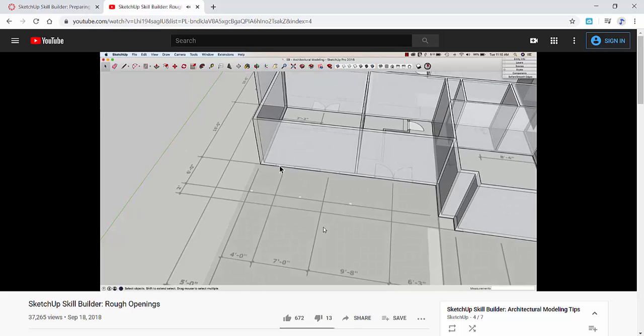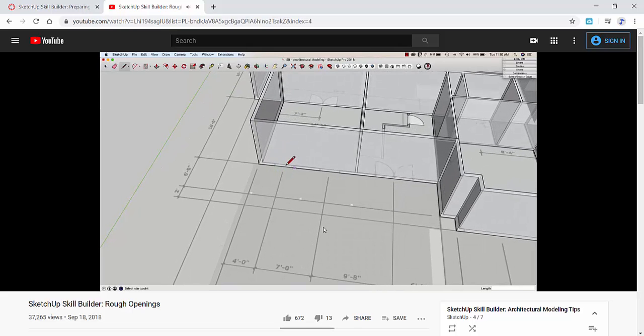So let's just hop in here and look. Right here, I have a window. It's about a 3-foot window, and I'm fairly certain that it's a 4-foot tall window. So this is a 3040, something like that is called out. Now there's a relationship between actual component size, your door or window finish size, and the rough opening that's required. I'm not going to get into all that stuff. For this example, for this window, I want a 3-foot wide, 4-foot tall window. I want a 3x4 hole cut in this wall, and I want the top of it to be at 7 feet. So who cares how you come by the numbers?